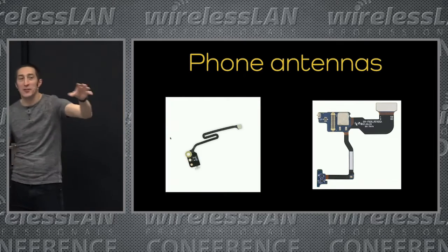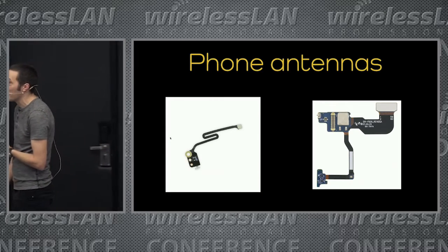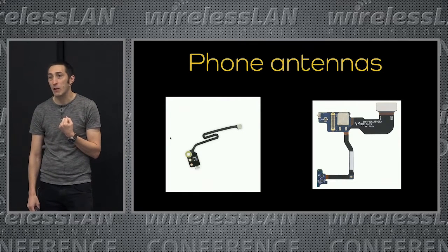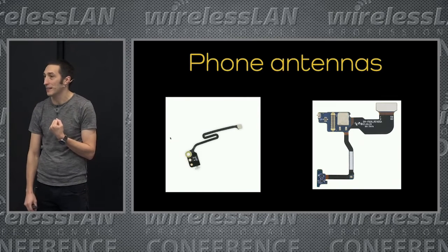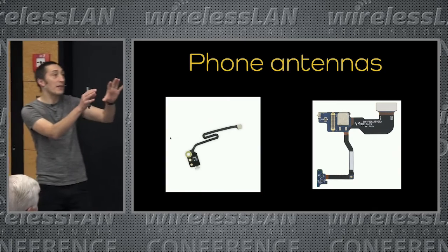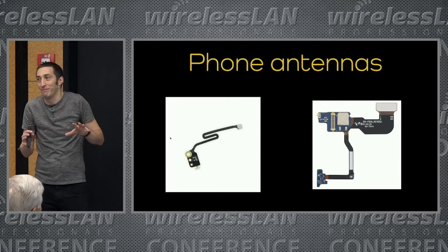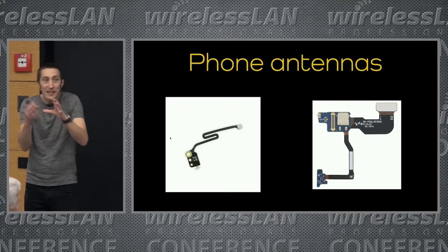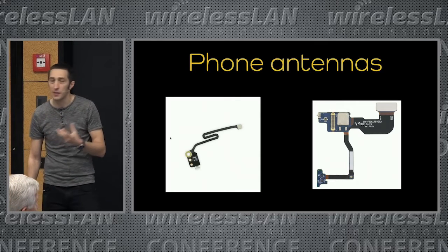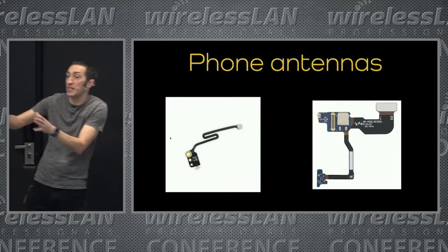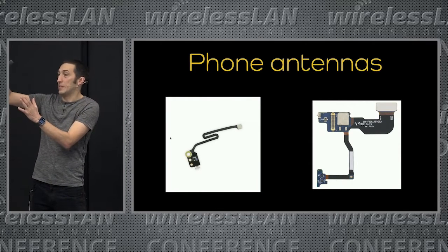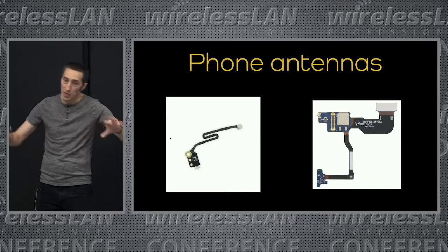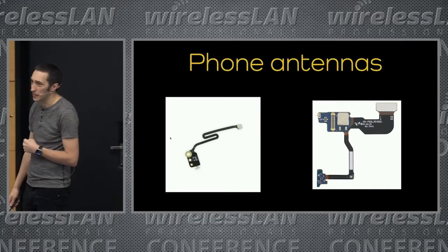Okay, so what they do is they build the antenna into the phone itself. But then to get it to fit, it ends up being bent. And when you bend an antenna, instead of getting a positive gain, you get a negative gain. So actually, whatever the signal strength is, we're going to receive it less, as a lower signal strength. So the RF circuitry is really going to affect how a device reads a signal. Not only are we using an inaccurate signal measurement, RSSI, and based upon what our chipset does, we've always got to think about the antenna and receive circuitry. And those two things combined are going to lead to very different signal readings.